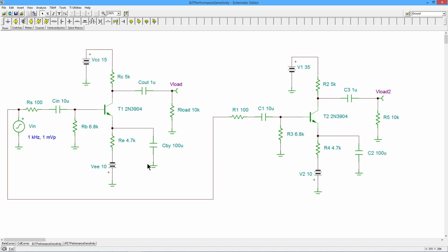When we look down here at the collector, the emitter area, with this bias, most of this 10 volts we know is going to drop across this emitter resistor. Ideally, this base would be 0. In reality, it'll be slightly negative. And then we'll have, of course, the 0.7 or thereabouts across the base-emitter. So maybe we'll get 9.2, 9.3 volts of this dropping across RE. That's going to give us somewhere in the 2 milliamp range with these values. Same exact thing over here.